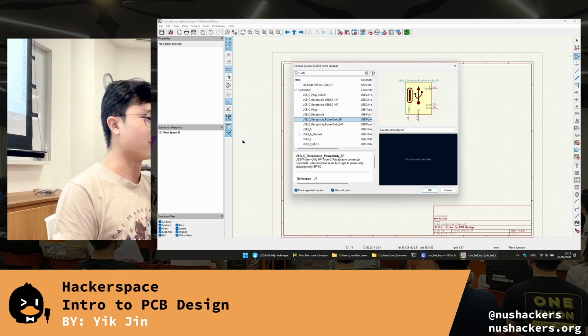You can see over here there's V-bus, which is your voltage, CC1 and CC2, which are your sensing pins. I'll go more in depth later. Then there's ground and there's shield. So this looks good, so I will just press OK.